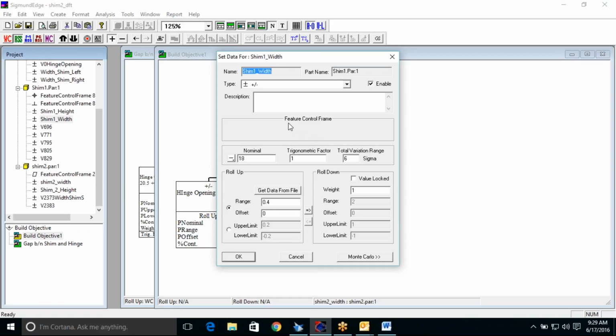And when you actually open any of these, it tells me where this is coming from, the name, and the type of tolerance. We support all the different geometric tolerances, and in addition you've got any plus-minus, linear, and alternate dimensions. You also see two additional types of tolerances that are not inside your CAD program. Those are float and custom tolerances.